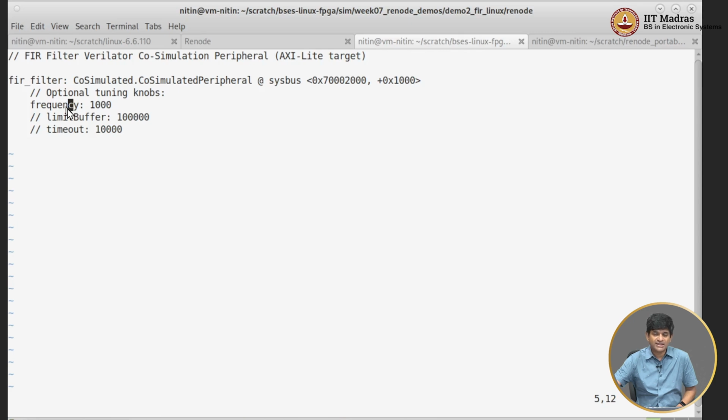If at all the bus tries to read from that, it just waits for the Verilog code to come back and say, okay, it has advanced. In the meantime, the bus will just basically freeze. It will keep the processor waiting until it has got data back. So nothing else really happens, and Renode is able to advance time much faster. This happens only when we actually try to communicate with this particular peripheral. At all other times when this peripheral is not active, the Renode simulation runs at its regular speed.